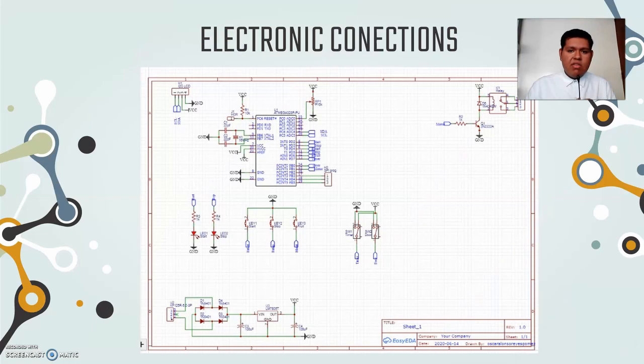Now the electric connections. Here's the diagram for the electronic parts with a microcontroller and all the external components that it requires to work. It also has the relay with the transistor to turn the AC motor on and off. It also has all the inputs, the switches for the door, the timer function, the LEDs to show messages, and the AC to DC conversion.